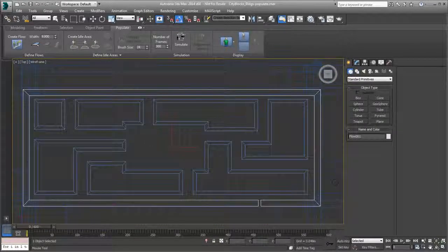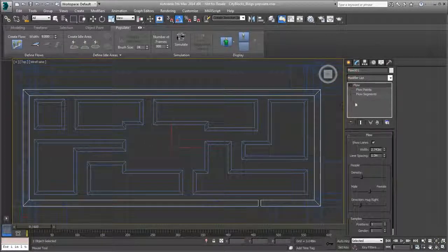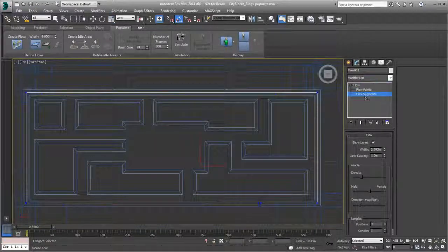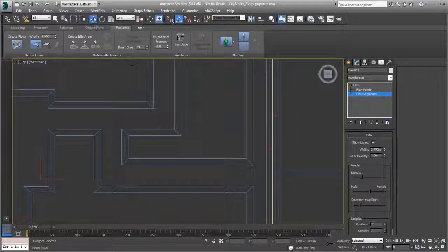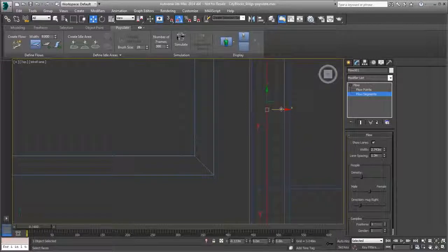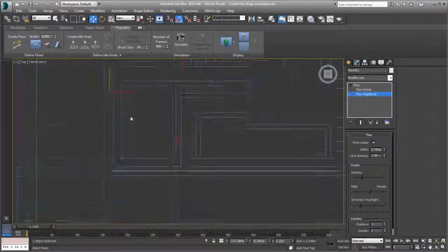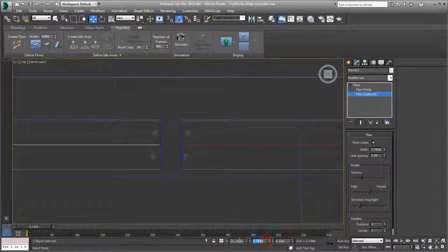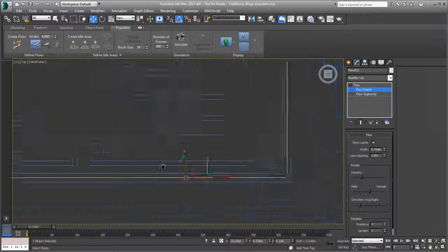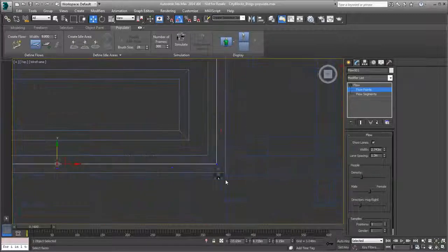In the Modify panel, expand the single entry to access sub-object mode. Make any necessary adjustments to the flow points and segments. Make sure you move flow points and segments based on individual pivot points. Adjust the start and end points so that they share the same location. Next, you adjust the corners by adding extra segments.